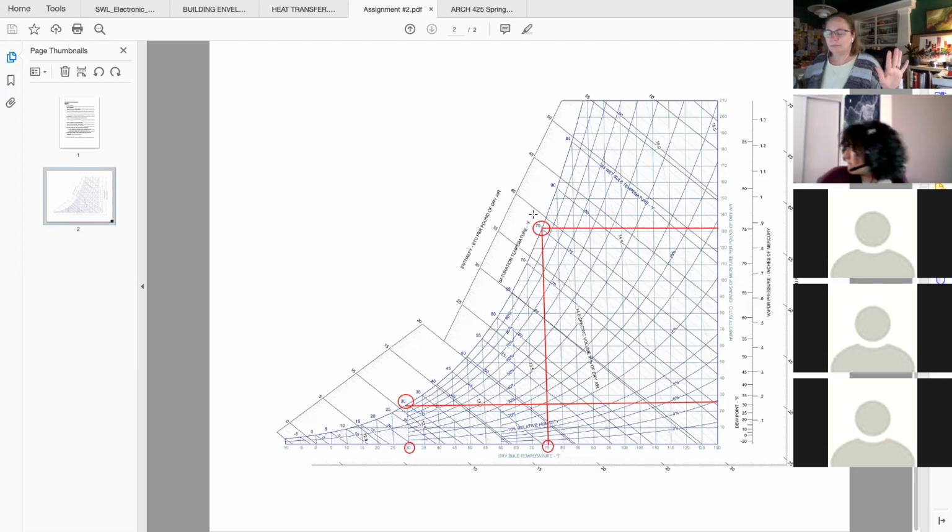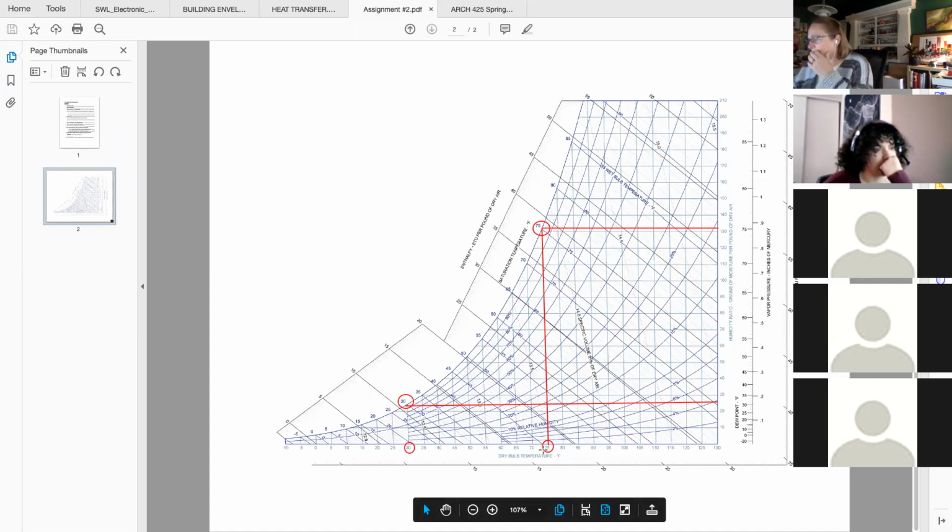Well, I guess if it's raining, like it's raining where I am right now, it is a current condition, but they're different. Weather does its own thing in terms of thermal comfort. It's a different subject. Chances are current temperature and humidity can affect the weather, but I'm not a meteorologist and I don't know a lot about that. So wet bulb temperature at 100% humidity equals your dry bulb temperature. Concentrate on your diagonal lines, your curved lines, and your horizontal and vertical values. The straight lines within the chart are just to help you read it a little bit better.